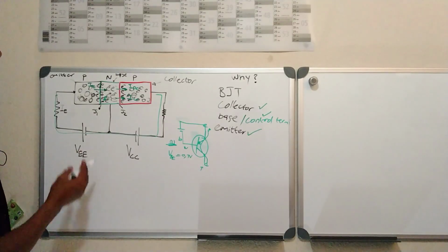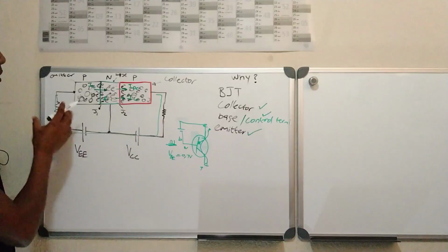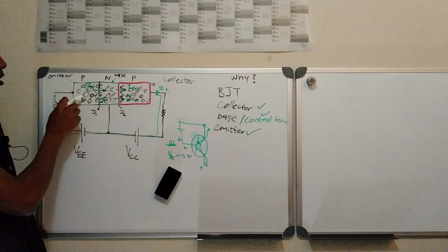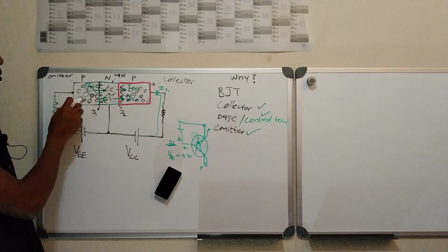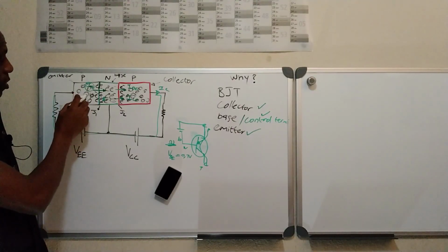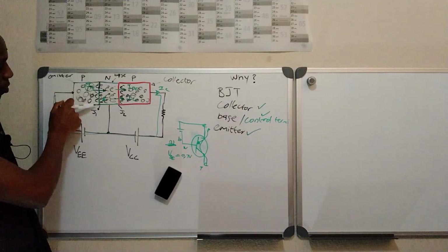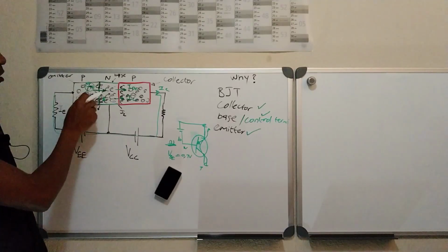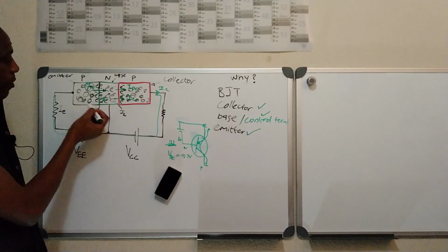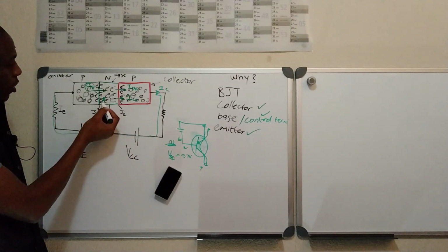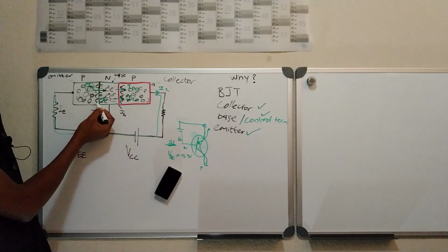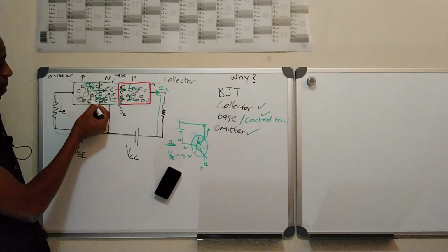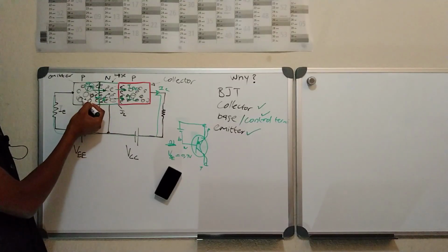So now let us put together all the currents that are generated through this emitter. IPE is a current that is produced when the positive charge carriers are diffused through the PN junction, or the base emitter junction. We also have another one that is generated when the negative charge carriers are diffused from the base to the emitter and they fuse with the positive charge carriers.